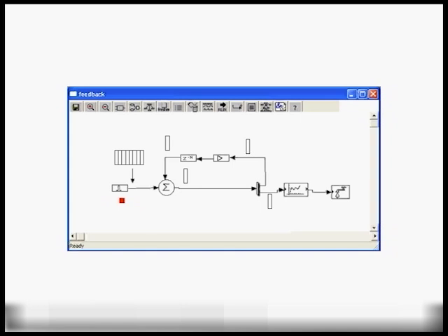So let's take a look what happens. The impulse block generates 128 samples. The add block sees that the delay block in this case outputs a 0 sample, so now it has one sample here, it has 128 samples here, and again the add block, in order to operate correctly, looks at the minimum number of samples on its input ports and only processes the minimum number of samples. So we have one sample from the delay block, we have 128 samples here, but it'll only process one because the only number of samples that the delay block outputted was only one sample. So the add block actually generates one sample.